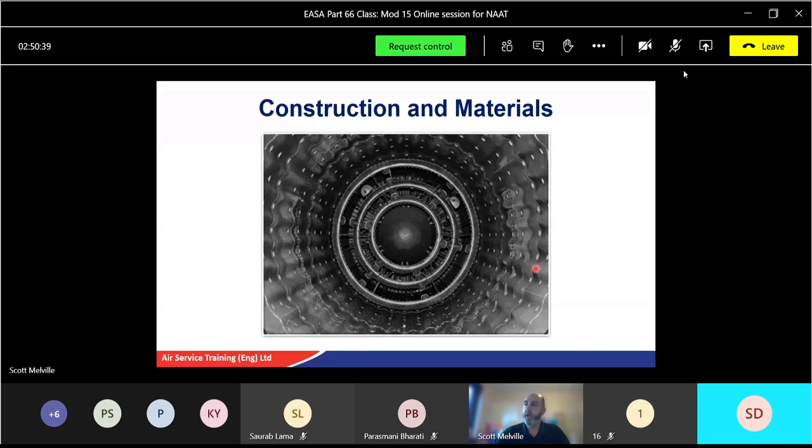Construction materials. That would be us looking up the exhaust, looking from the back. You can just see the turbine in the back here. But this exhaust system actually has reheat in it. These little extra bits, we'll cover reheat in a little while, don't worry about it. But there's the exhaust cone. Don't worry about these manifolds at the moment. This is a military aircraft. As you can see, the blades of the turbine, which would obviously be the LP turbine.